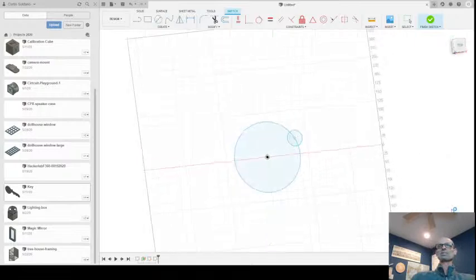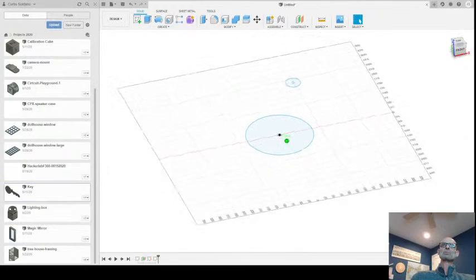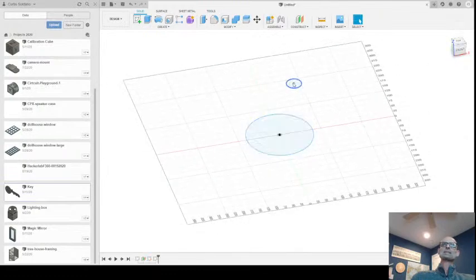And I'm going to click Finish Sketch. All right, so now 150 millimeters above this plane, this new object is sketched upon that phantom construction plane. It's like this first plane, but it's 150 millimeters up. And so now I can do things instead of that uniform extrude that would just extrude this circle upward.